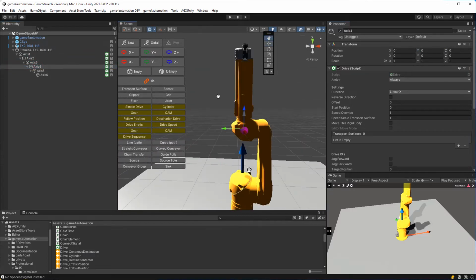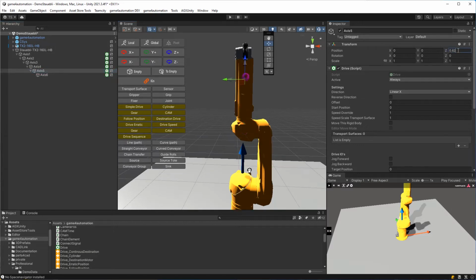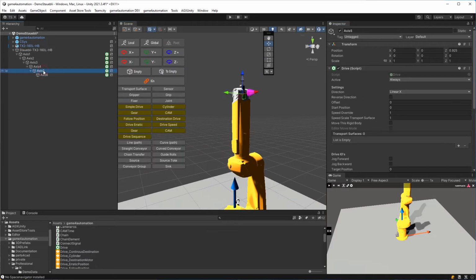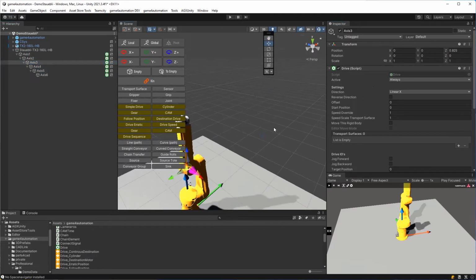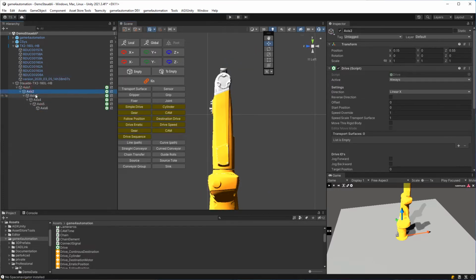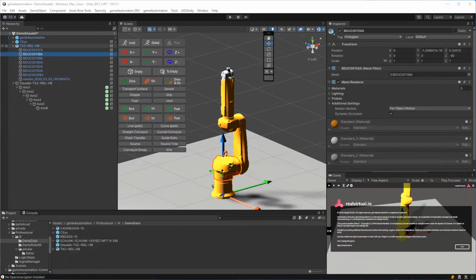We are now going to do this in fast forward mode for all the axes. So we take the values out of the datasheet and we are going to position the still empty game objects to the positions where they need to be. So the 0 point of the axis needs to be in the rotation point. So we now defined all the axes, and the rotation of all the game objects is 0. So same oriented as the base coordinate system.